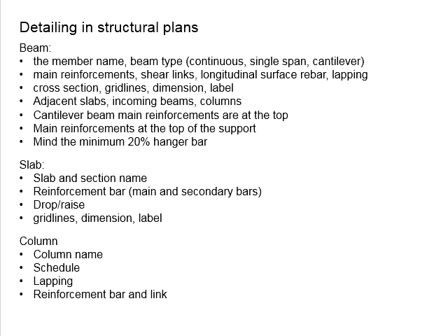There will be a solid line in front of the beam to indicate that you can see the edge of the slab, which in this case will be the top and soffit of the slab. And there will be a hidden line to represent that the slab is actually behind the beam. The hidden line will represent the top and the soffit of the slab behind the beam.